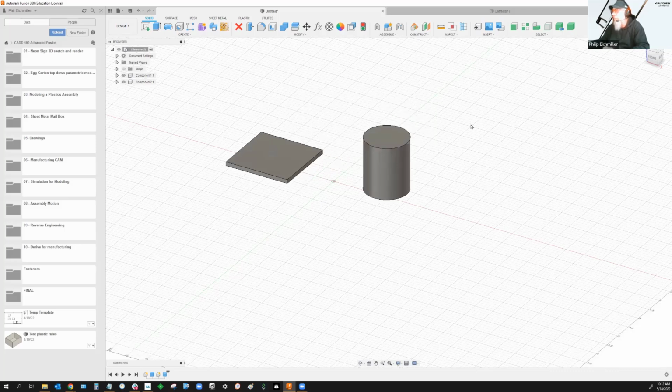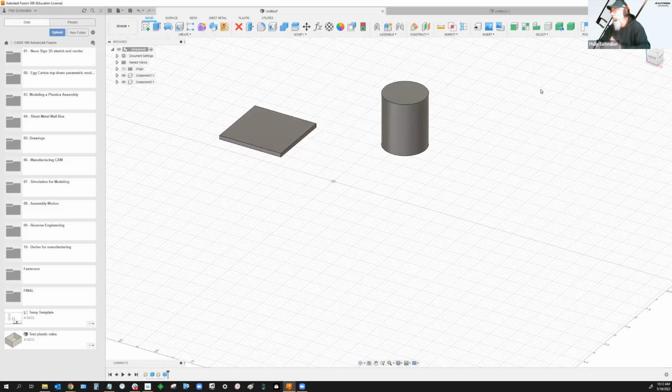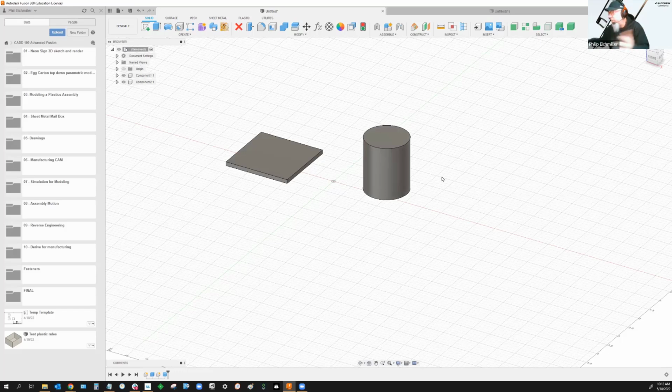Now, the way Fusion handles this freedom of movement is seen here in this capture and revert position. So putting this in Inventor terms, if you move components in an assembly, you'll see the little invisible Gorilla Glue snot that connects everything up. And when you rebuild that assembly, everything goes right back to where it was. That's exactly the same thing you're doing right here in Fusion, 100% exactly the same, except you don't have to start a move command in order to do it. And revert is as simple as that, or rebuild the assembly.